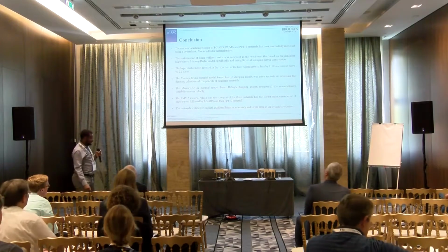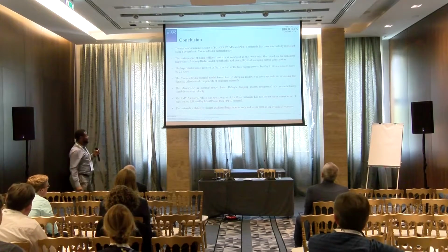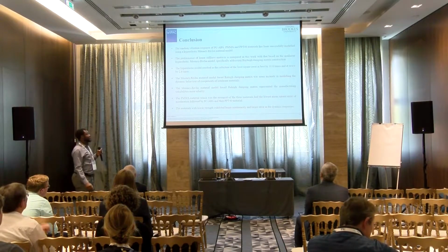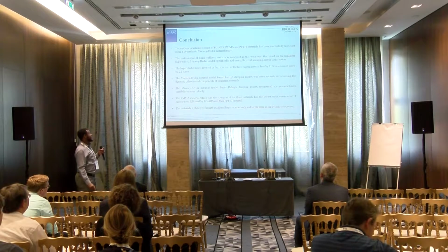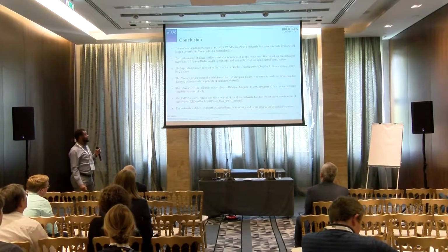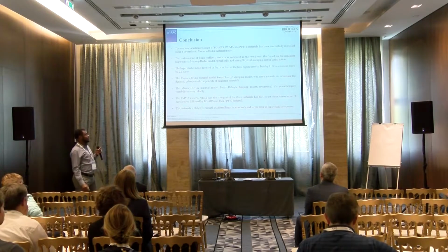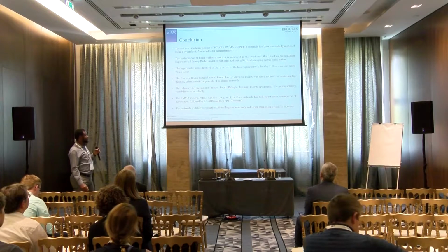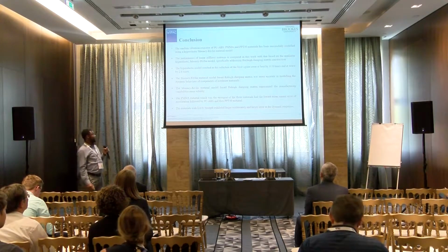In conclusion, the random vibration response of PCABS, PMMA, and PBT materials has been successfully modeled using a hyperelastic Mooney-Rivlin material model. The performance of linear stiffness matrices is compared in this work with that based on the nonlinear hyperelastic Mooney-Rivlin model, specifically addressing the Rayleigh damping matrix construction.